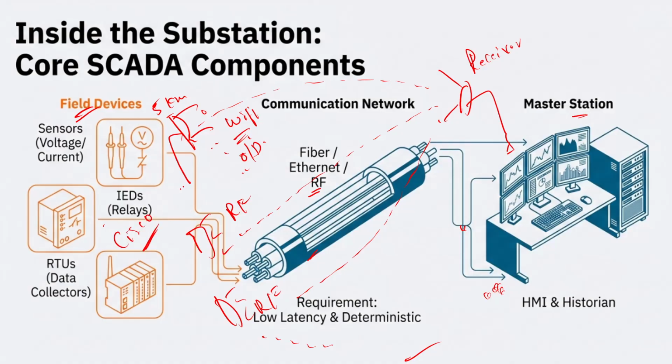Cisco makes these outdoor Wi-Fi devices, and we also have HP Aruba, Ruckus. These are all the major OEMs who make these devices, and we can purchase them and install them in the field site, and then we can easily communicate the data from the field devices to the master devices, right? So this is one way.